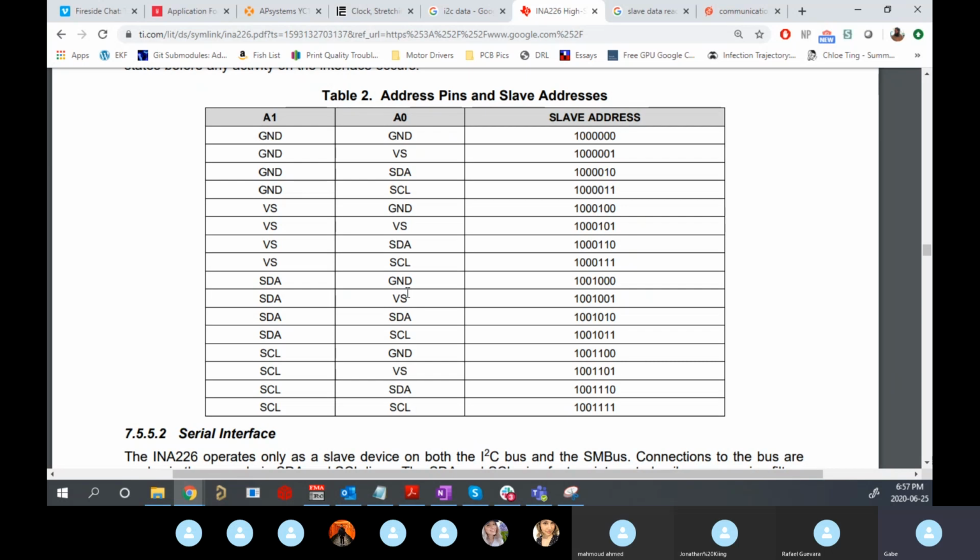Yeah, that makes sense. But theoretically, if you wanted, you could use 3 different sensors, if they have the capability, set them all to the same slave address, and then in your communication protocol, you could add an extra layer of info saying, hey, are you this new address I made up, ABCD? And then the slave would have to reply. But then the slave would also need to know how to reply to that. So it'd be a lot of work, and you'd have to reprogram the chip, and things wouldn't work so well.